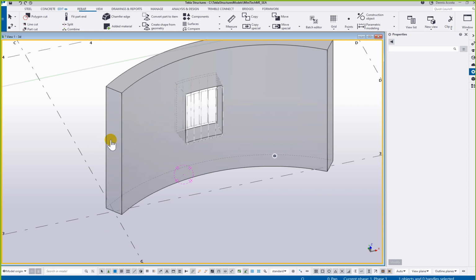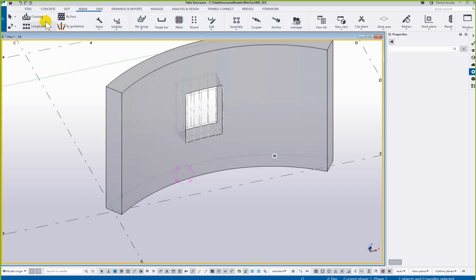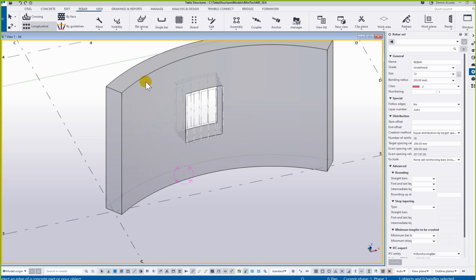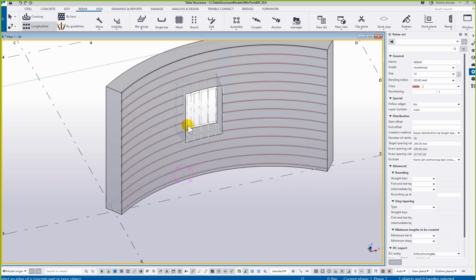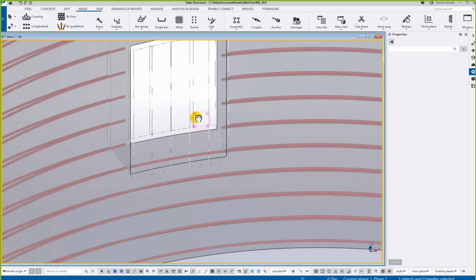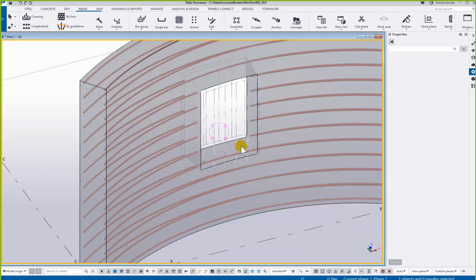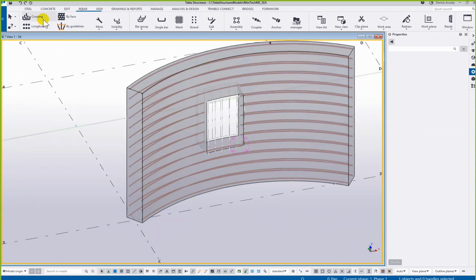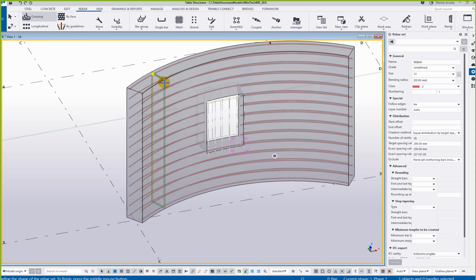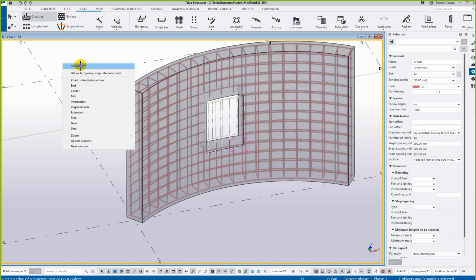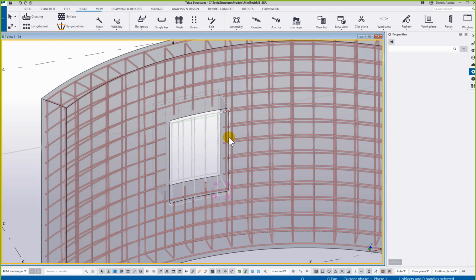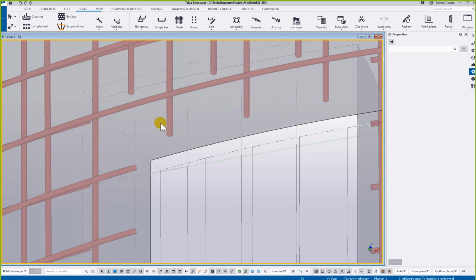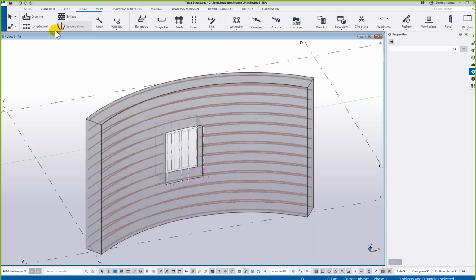Just hold on. Okay, longitudinal bar. So click on this and then pick it. So longitudinal bar. There you go. If you notice here, it will cut automatically. And then for the crossbar, there you go. So it cuts automatically. But again, here, if you want to close this one, then you can use the guideline.